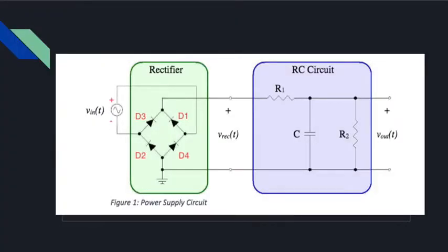Now let's take a look at the two circuits together. So if we look at Vin and assume it is input cosine, when it's positive, it will go up and around and then reach the rectifier circuit in between D4 and D1, and it'll go through D1, and then it'll travel through the RC circuit and come back around and go through D2 and go back into the negative side.